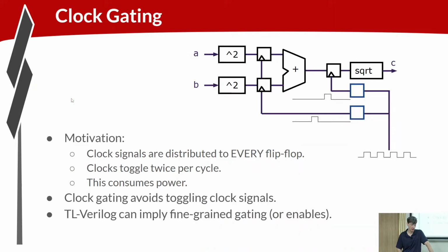And therefore, we can generate a circuit that disables the clock edges for the invalid cycles. Okay, so in this case, with the pipelined logic and the knowledge of validity, we're going to get pulses that look like this. So these pulses correspond to a valid calculation when the valid signal is asserted.